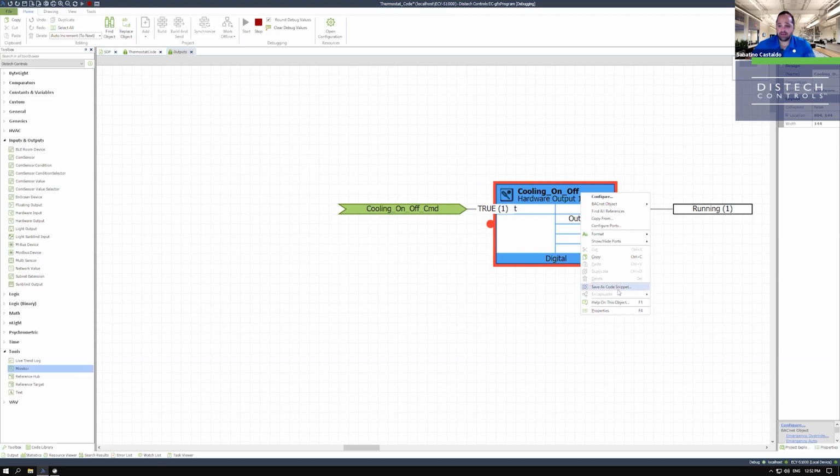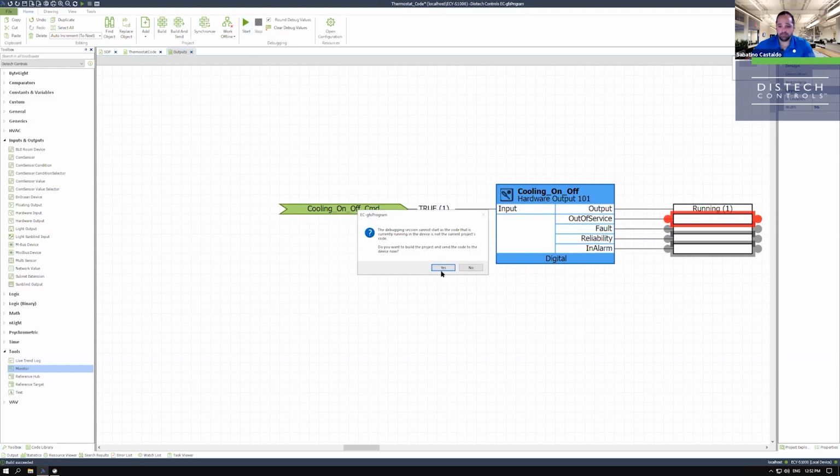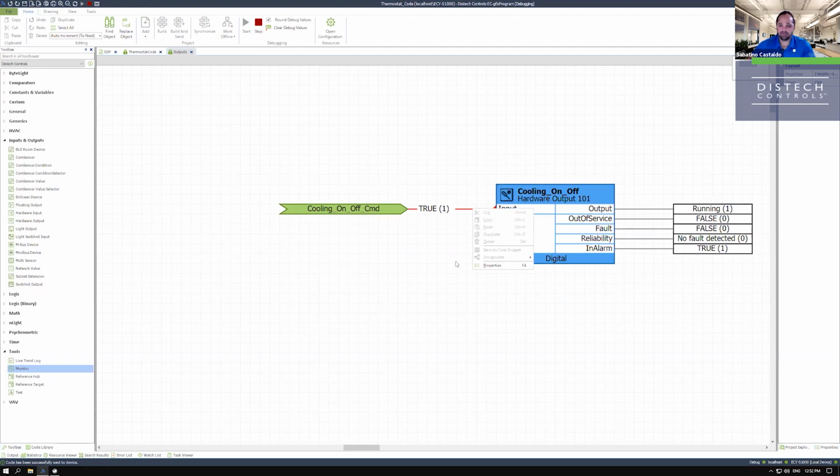Now I can't add ports or make changes to the code, but I could just change items in the object. I would have to stop this, right click, monitor all, and then push play again. That's fairly simple enough to do. It's just a step you have to take. Just you can't modify running code. You can't delete a line. I can't take this and delete it. Of course, you can break a lot of things. So it's got to be compiled. It's got to be analyzed and sent down. That's what happened here.